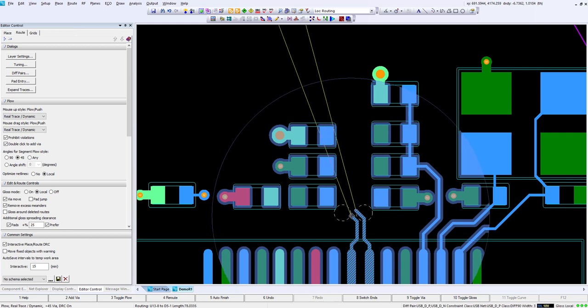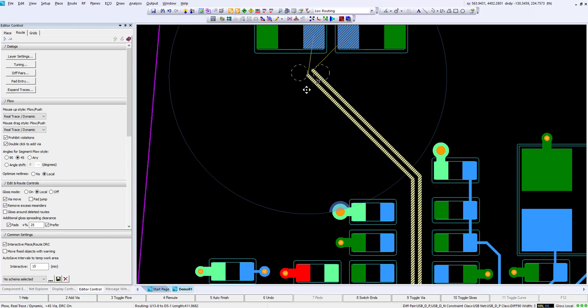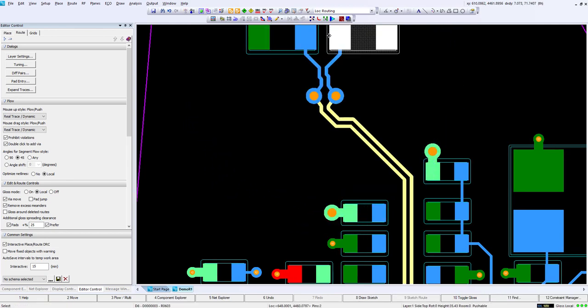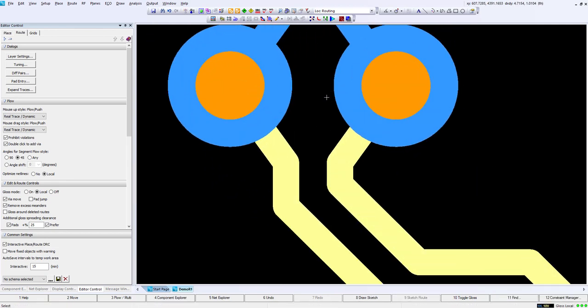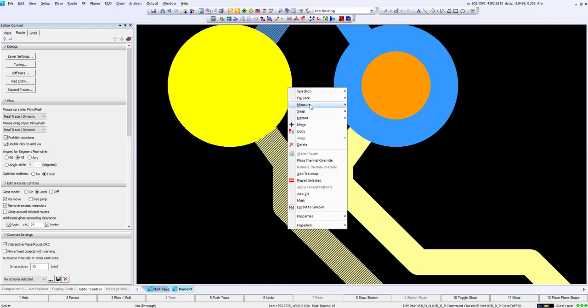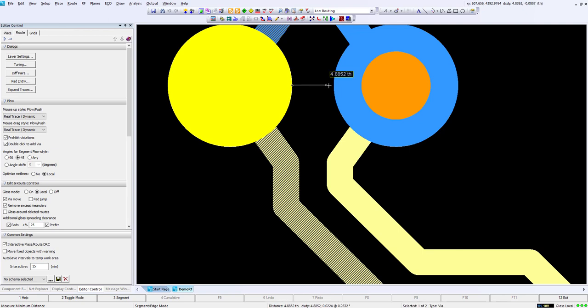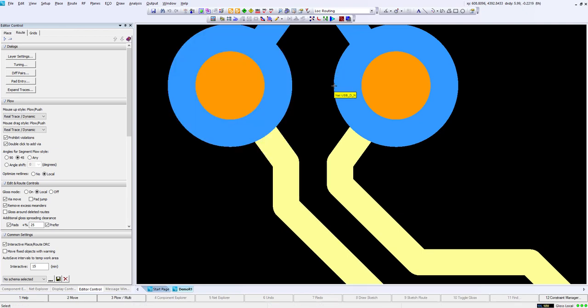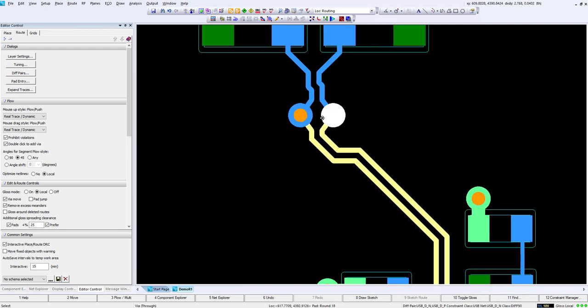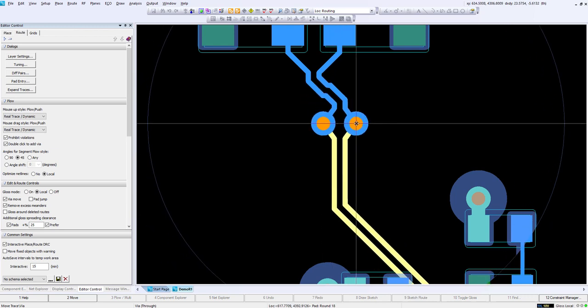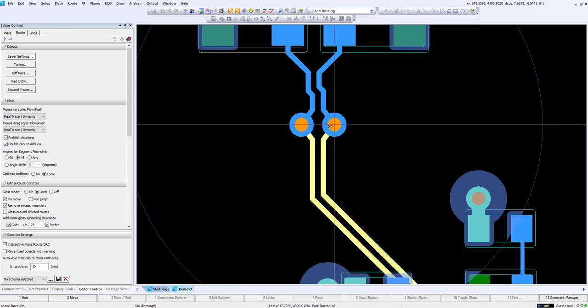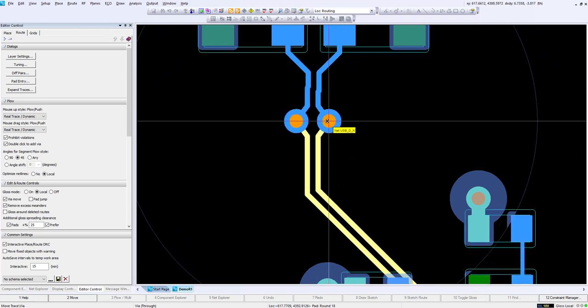All right, we'll go ahead and route our differential pair to show the via spacing. Come up towards the top. Now we'll notice that the spacing here is 6. In fact, I can measure that. Minimum distance. You can see it's 6 instead of the 10 or 12 that I have in my design rules. And then a nice feature is if I pick up one of the vias, it automatically picks up the other two, and then it does adjustments on the differential pairs as needed.